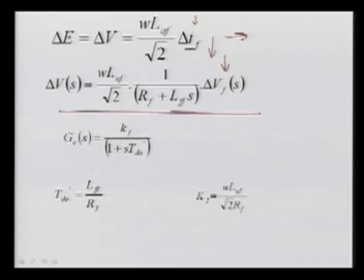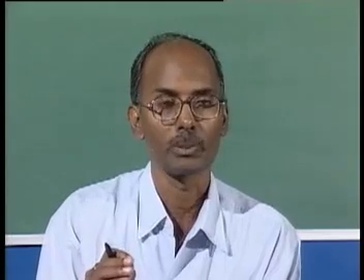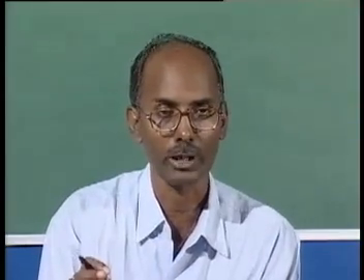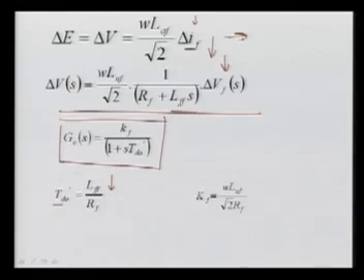So we can write the complete transfer function here. Now, why have I written Td0 prime? The Td0 prime is Lff upon Rf. When the armature is open circuited, with no current flowing there, the time constant of the field, this Lff upon Rf, is called Td0 prime.